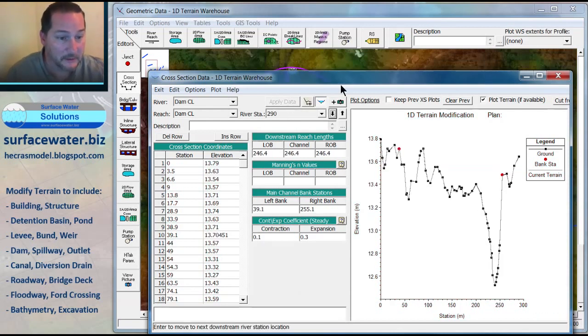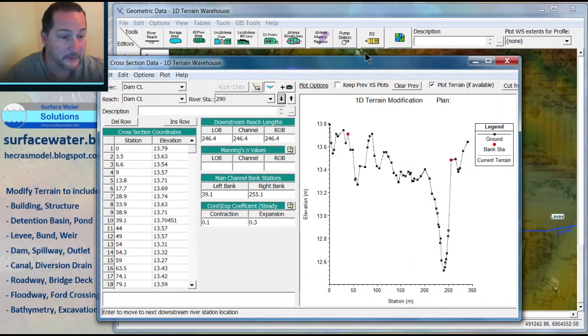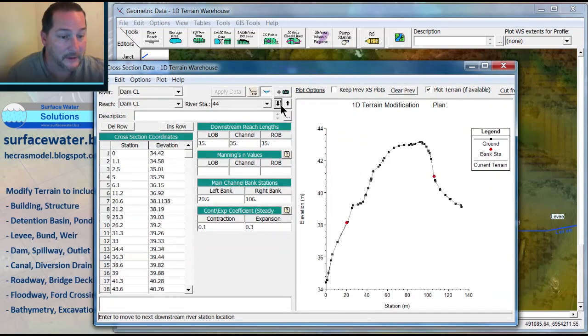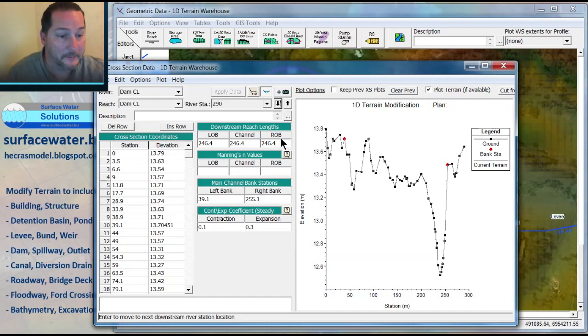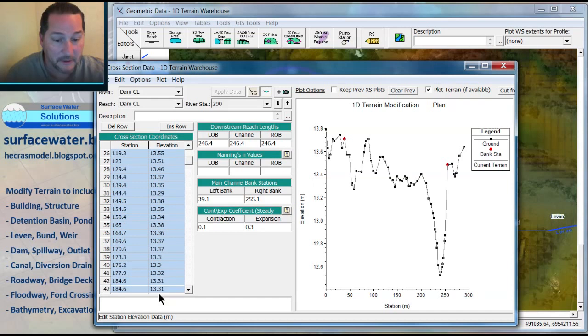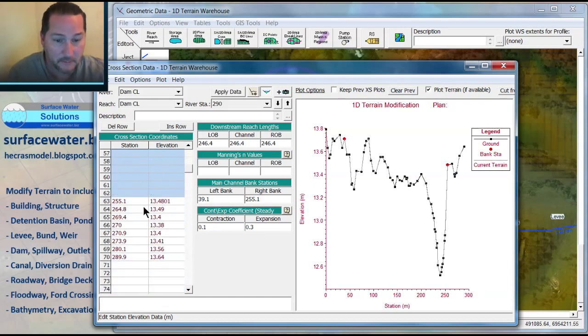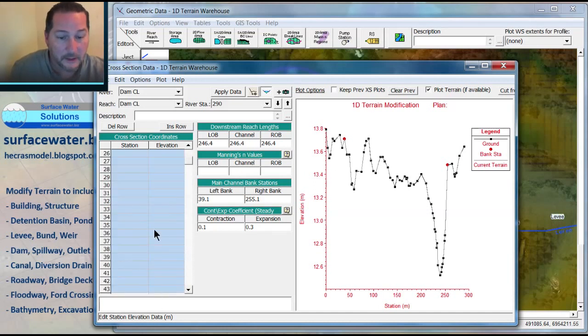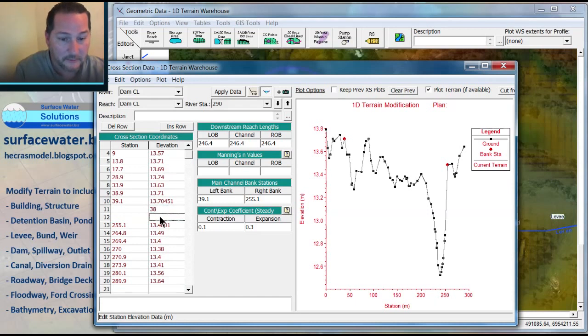Do the same thing in the middle, and I can see where I'm at right there in the middle. This is going to come way up. This is a cross section going right across the middle of my channel, so I need to come back up to the elevation that I was at right here, which is 38. So I'm going to make a 38 meter high dam right in the middle of this and go blowing out my sections in between right there. Take my end data past that and put in my dam at an elevation of 38. And again, I can make this slope up as much as I'd like. I'm going to pull this one up maybe to 100 and to 200. This is going to be a big fat dam in the middle. Let's make this a little narrower.